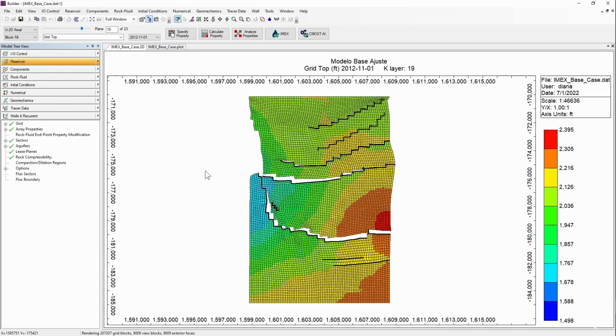The grid-independent wells can be rotated and shifted, which can make parameterization through CMOS possible without requiring running Builder silently. So a well that is independent of a grid simplifies the CMOS studies where rotating and shifting the wells is important in the study. This option is available for grid-independent wells and allows us to reallocate the well without modifying the original trajectory and perforation measured depth intervals.